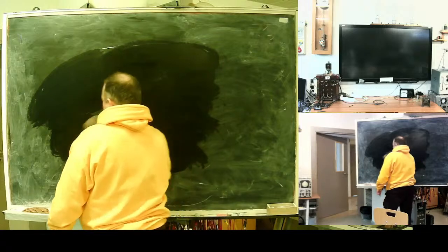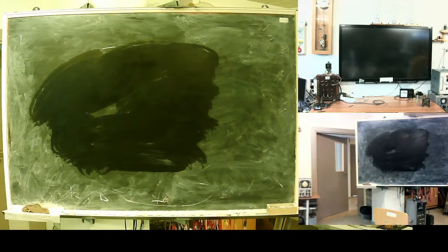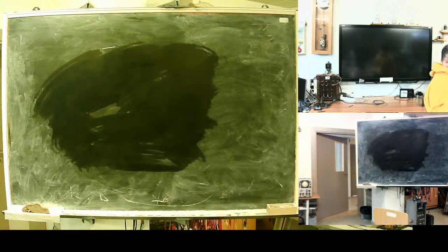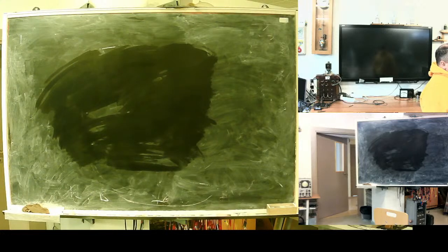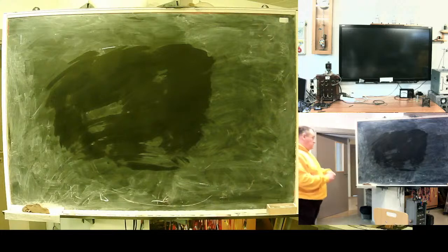Also, nowadays you can find field sensors, special antennas which can harvest the H component of the electromagnetic field, and can be placed under the wire. No precision, but they show the direction of the fault.